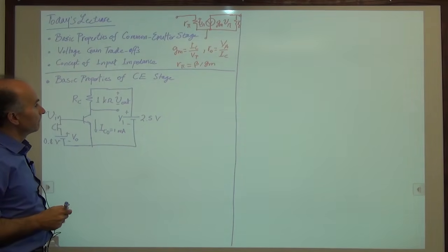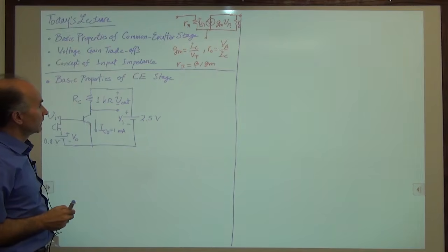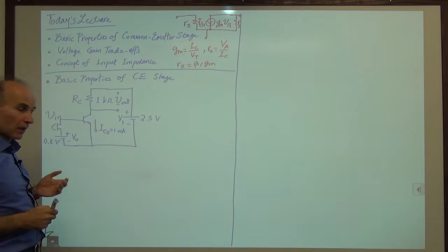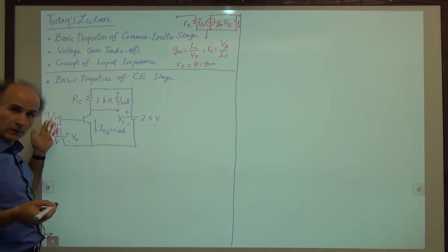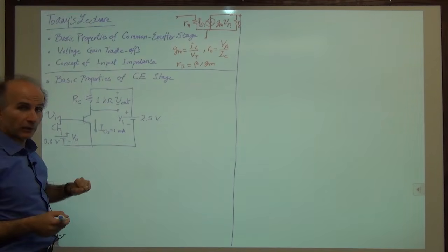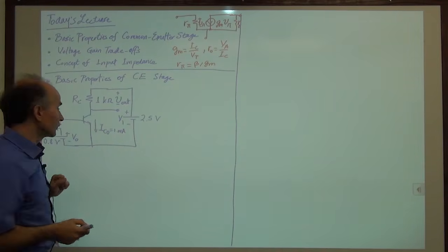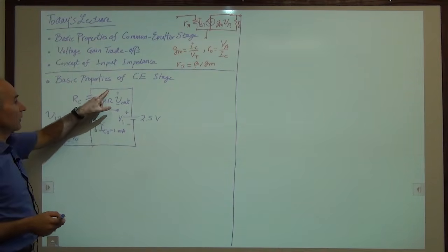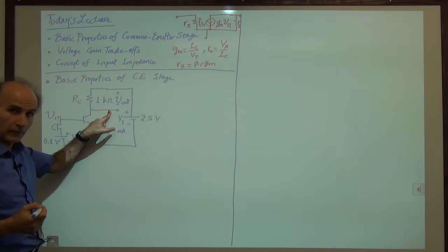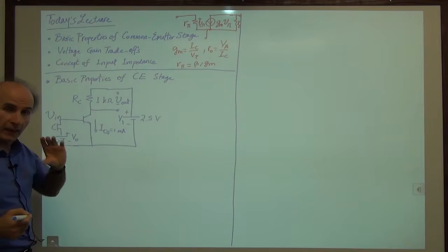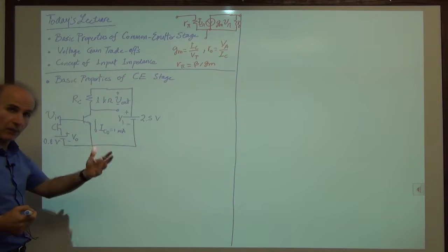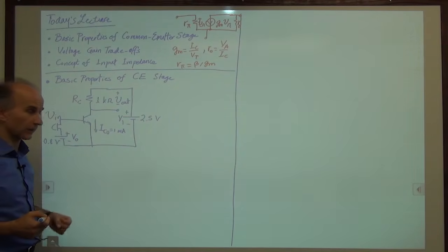Okay, so let's go ahead and plot these as a function of time. Let's say the input is a sinusoid of some sort, so maybe a millivolt or something in amplitude. And then we'd like to plot V out. And in doing so, we want to plot everything that we observe here, not just the changes in the output voltage. So for that, I would use an uppercase notation for V in and V out, because uppercase means everything, the bias and the signal change, etc.